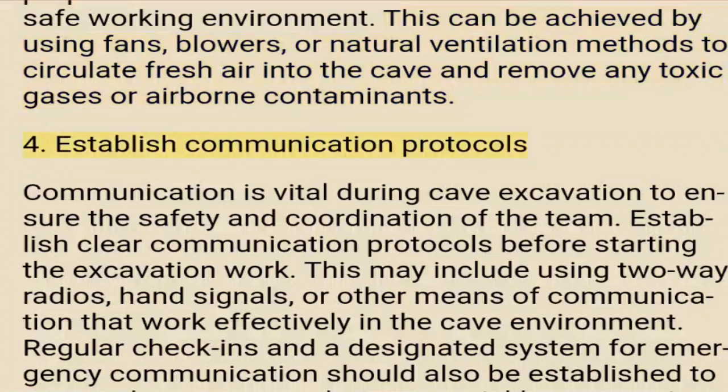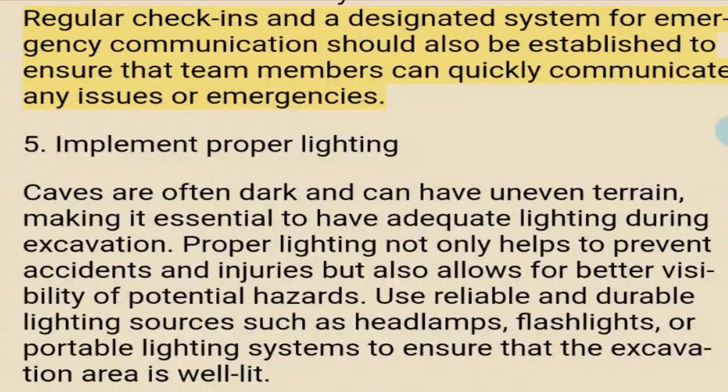4. Establish communication protocols. Communication is vital during cave excavation to ensure the safety and coordination of the team. Establish clear communication protocols before starting the excavation work. This may include using two-way radios, hand signals, or other means of communication that work effectively in the cave environment. Regular check-ins and a designated system for emergency communication should also be established to ensure that team members can quickly communicate any issues or emergencies.